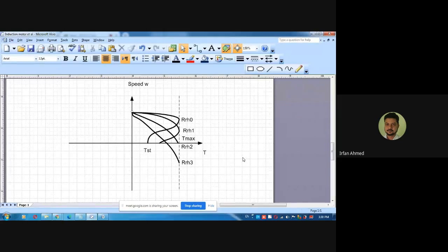There are now two flows of power. One flow is for the active power. The active power will flow from the generator to the supply and/or load. You can have a supply, a generator, and also a load in parallel. The reactive power will flow from the supply to the generator. Active power out of the generator, reactive power into the generator. Was I able to explain that properly?